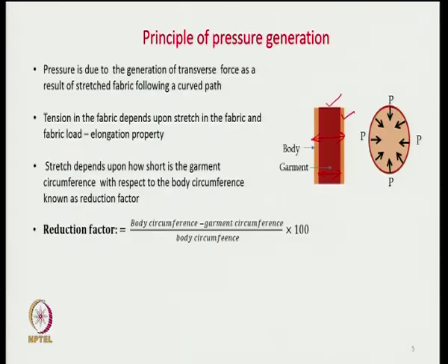That means the fabric will be under tension, and because of this tension, this transverse force will be generated. So, tension development will depend on the level of stretch in the fabric and the load elongation behavior of the fabric, that is stress strain, or we can say force elongation, because the elongation will decide how much force will be generated in the fabric.